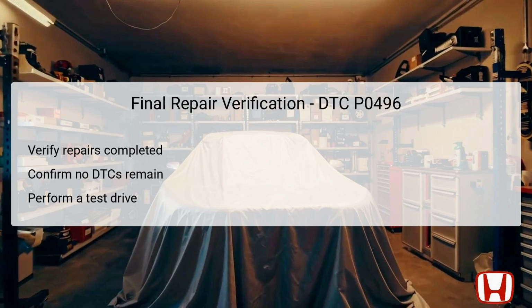Next, perform a test drive under conditions similar to those which may have triggered the original fault. Monitoring the system during this test will verify if the repairs have fixed the high purge flow condition or whether further issues need addressing. If all systems operate normally, and the MIL remains off, then the repairs can be considered successful.